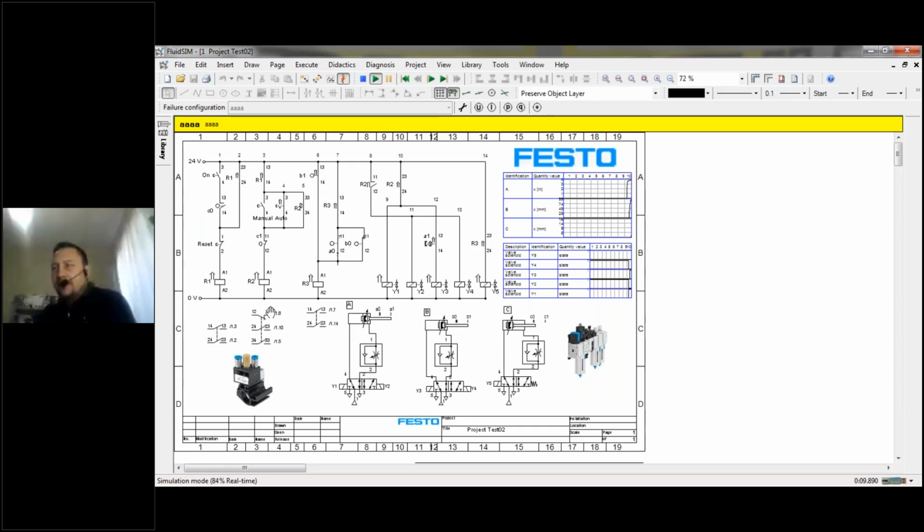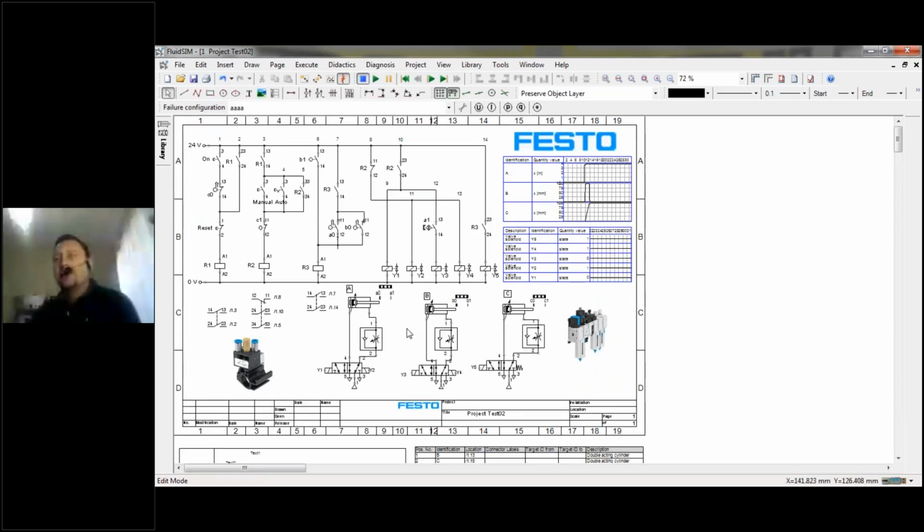Okay, there we can see it doesn't return. This cylinder has an internal leakage. All the air from the left-hand side goes to the outlet, through the cylinder, and that's why this does not come back. So we can complete our sequence. That is how you simulate the faults. I know we are quite fast in this webinar, but when we actually do the course, we will follow you step by step.